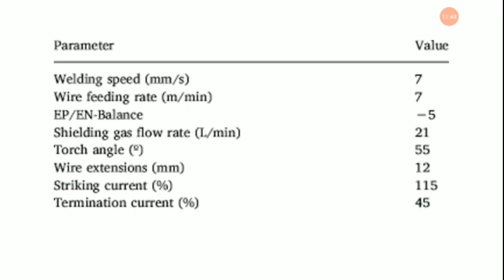Now coming to the effect on face width. The face width was considered as the quality characteristic with the concept of the smaller the better. The average values of face width for each parameter at levels 1, 2 and 3 for raw data are plotted. From this, the peak current, welding speed, pulse on time and gas flow rate are the most significant process parameters compared to the other process parameters. It shows that with the increase in peak current up to 200 ampere, the face width value decreases, and face width value increases with further increase in IP value.